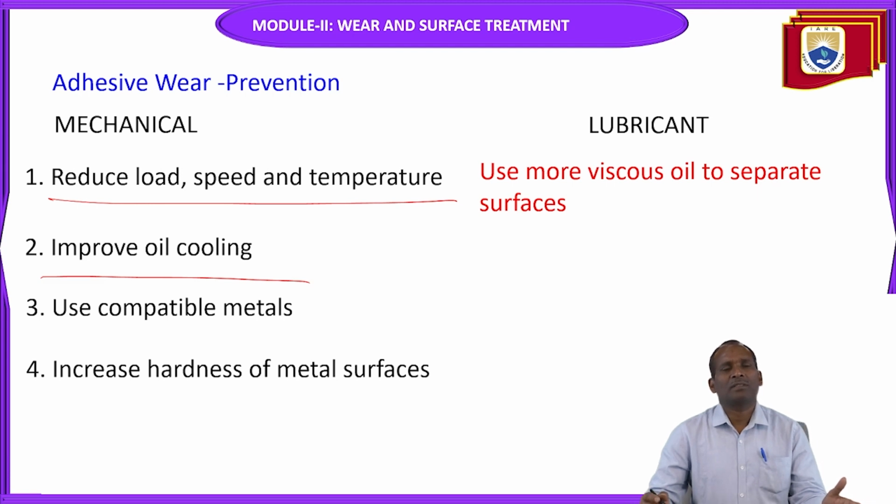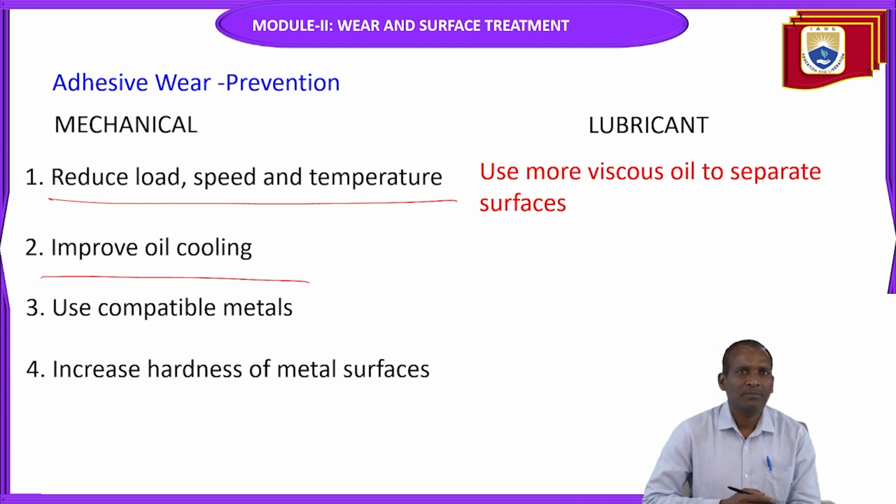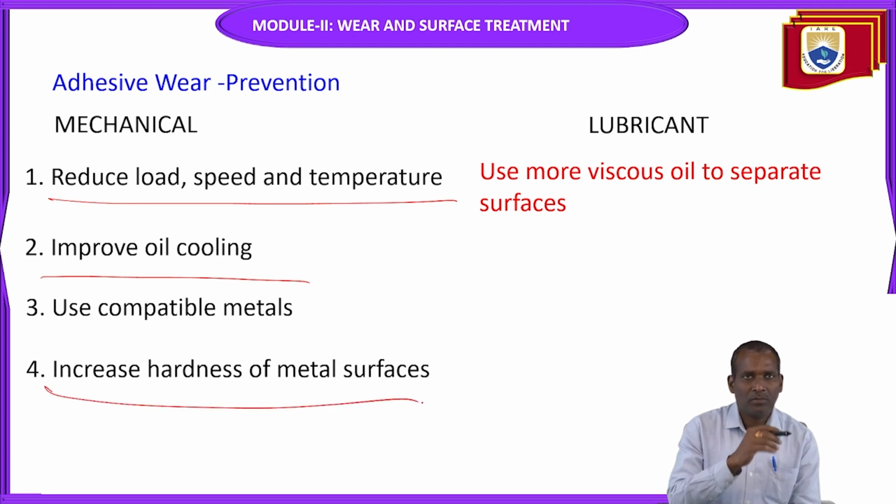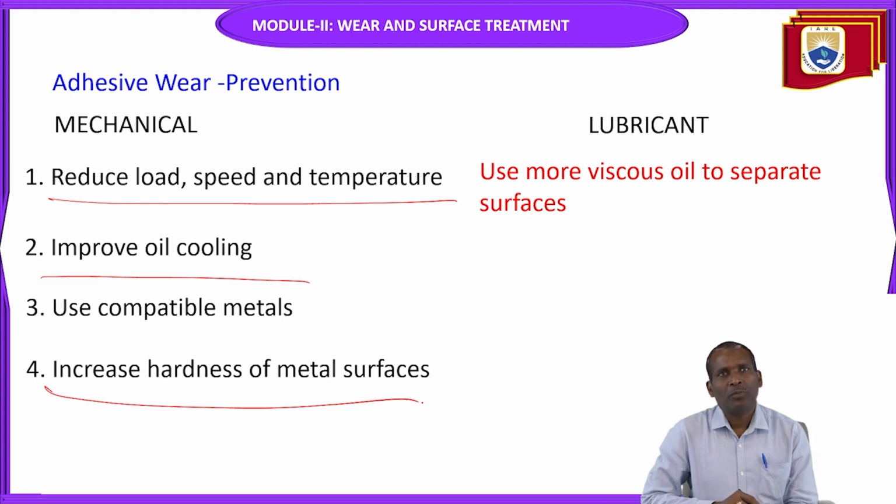The properties of the two surface metals should match. Otherwise, a chemical reaction between the two surfaces will be possible. Increase the hardness of the metal surface to prevent this adhesive wear.